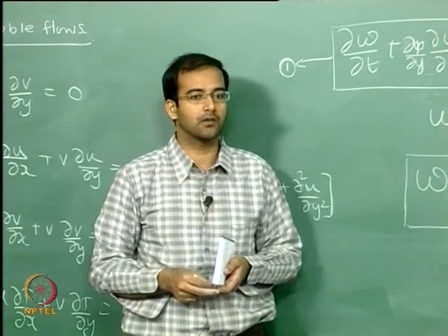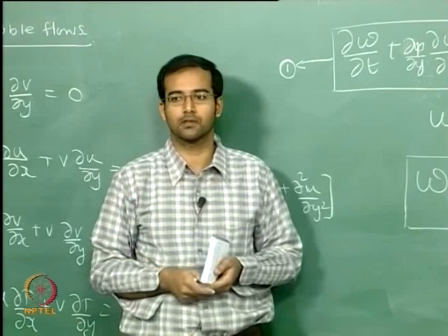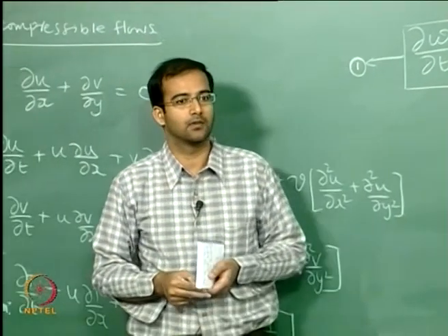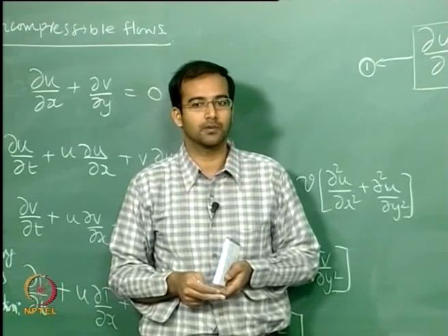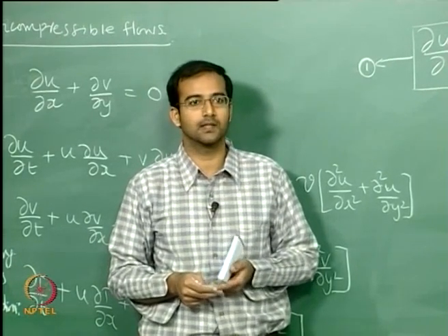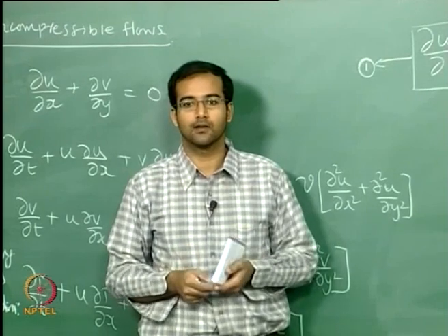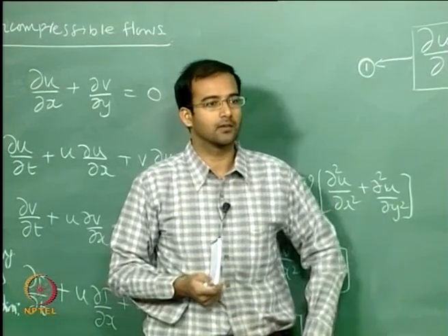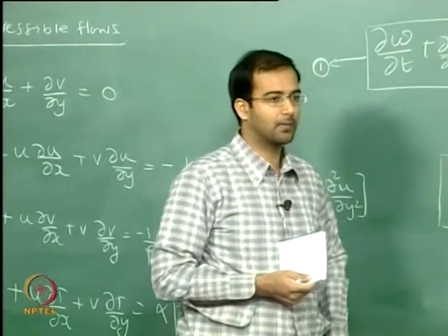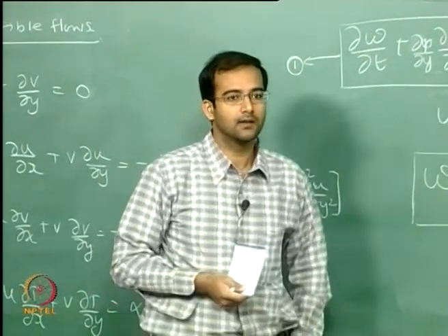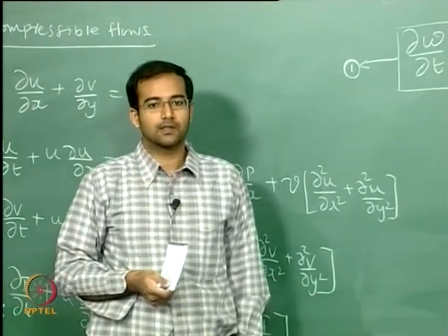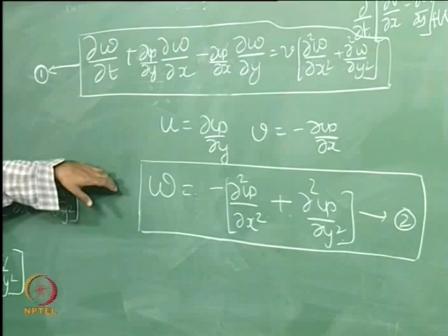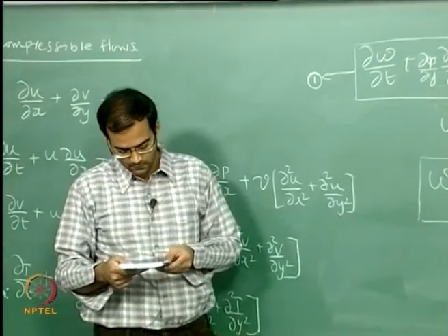So where you have to solve for three equations and you don't have an equation for pressure. That's why it's a very popular technique for numerical solution to two-dimensional incompressible flows. Most of the journal papers that you take for 2D incompressible flows, until recently, where you didn't have powerful computing facility to solve the full Navier-Stokes equations, were employing the stream function vorticity technique. And this is what you are going to try out also.